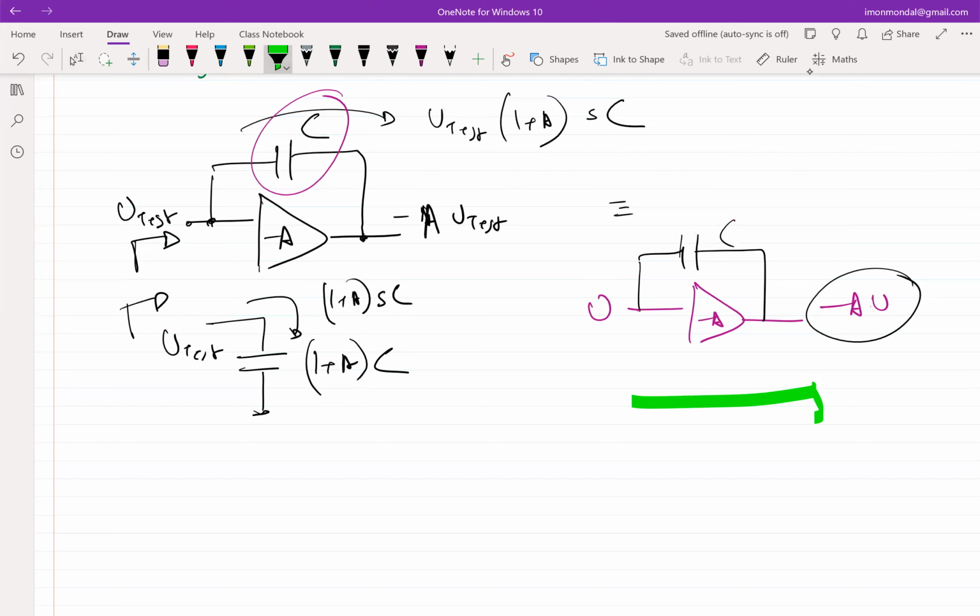So the argument is, you cannot get an ideal voltage controlled voltage source. What is an approximate voltage controlled voltage source? It is something where even if you connect something at the output, it doesn't really change whatever you are getting at the output, right? So whatever you connect doesn't load. That's what it means, right?